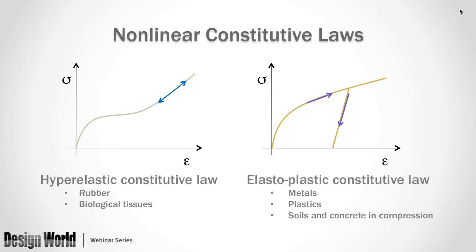So the user interface will capture the theory behind it without too much pain. The second part I'd like to talk about is nonlinear constitutive laws. This is the material nonlinearity that we talked about before. And we roughly categorize it in two different categories: hyperelastic constitutive laws and elasto-plastic constitutive laws.